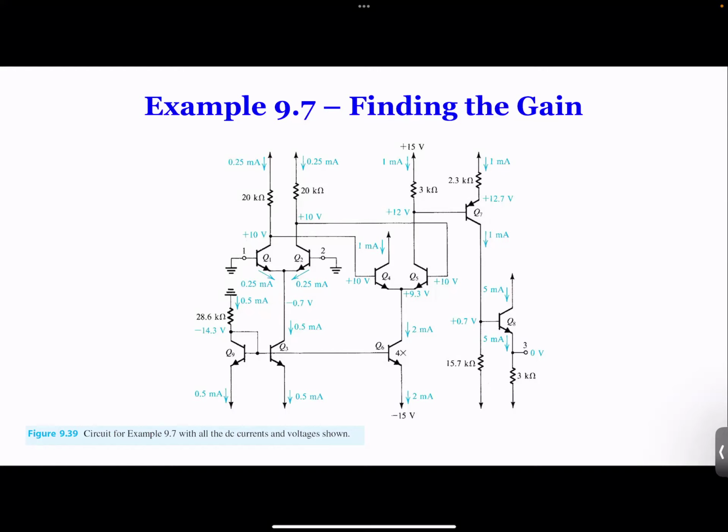So this is interesting. When you calculate the BJT, sometimes we assume beta is infinity, and sometimes we don't. We cannot. When you do the DC biasing, beta does not make a huge difference. It's only 1%, because beta is typically 100. So beta over beta plus 1 is 0.99, right? So it's 1% difference. So for DC biasing, often you can neglect the beta. Just assume it's very big.